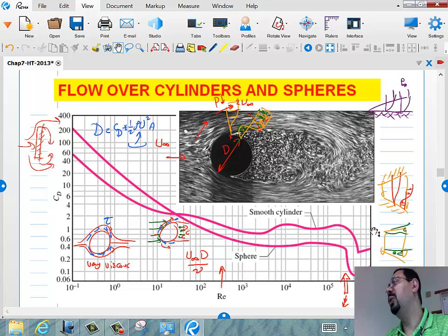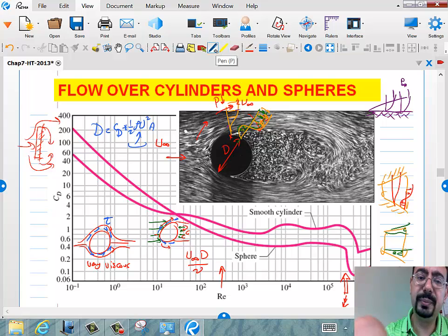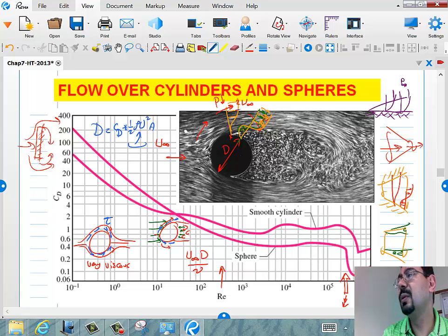Why? When you go into a nozzle, what do you expect the velocity to do? The velocity will increase, and according to Bernoulli, if the velocity increases, the pressure will decrease. The energy is conserved, basically. So P over rho is basically related to V squared. If you make the velocity increase because the area is getting smaller and smaller, who's paying? The pressure will pay. P over rho will actually end up dropping. So that's why we call this a nozzle, because it speeds the flow and reduces the pressure.